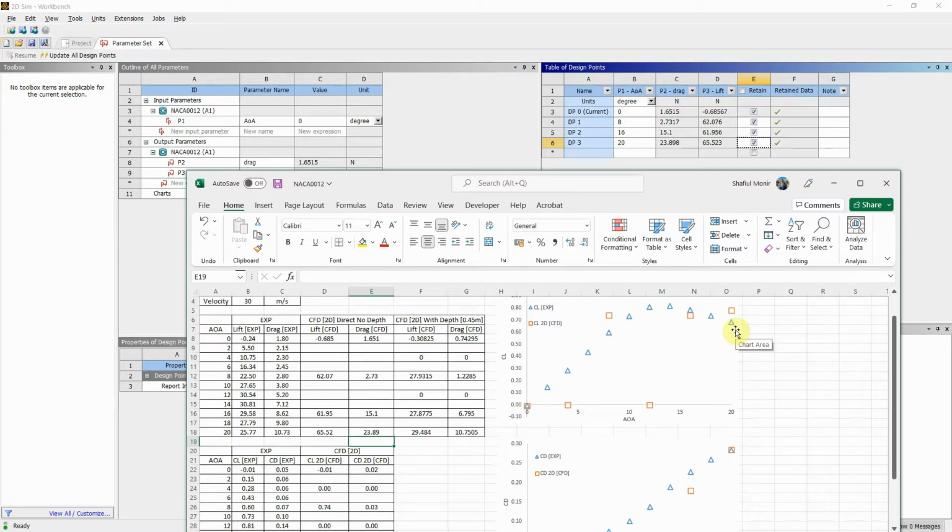But fundamentally, once you get your best results for the best turbulence model and the best mesh, I would then do all the angles for that model in order to show the final results of CL and CD with all the angles and your CFD results. And that's the one that I would put in the end conclusion of your 2D simulation in your assignment.